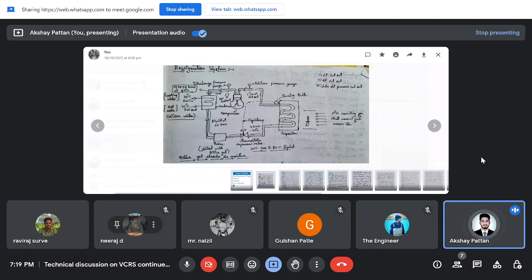So the high pressure cutout doesn't act immediately. Some of the high pressure is transferred towards the condenser. So to prevent the condenser from damage, the relief valve is releasing the excess pressure and sending the limited pressure, or set pressure, to the condenser.